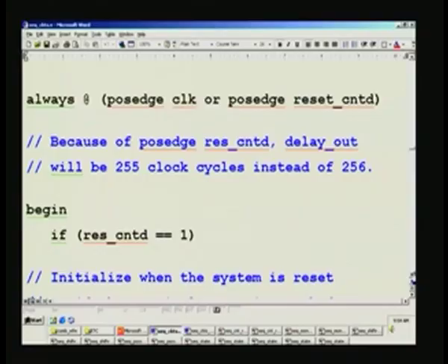Is this the way, where previously you set it as 0 and then you check if it's 1? Yes, my answer still is valid for that. We are sensing the level, but taking a decision only at the next clock pulse, because we don't have means of doing it without violating the RTL coding guidelines, right.